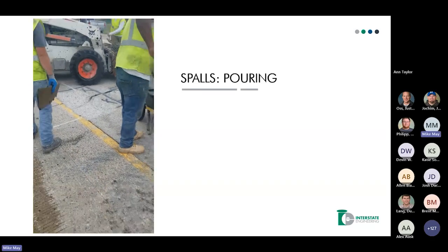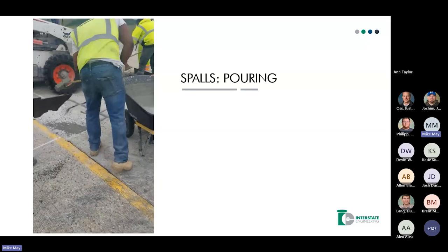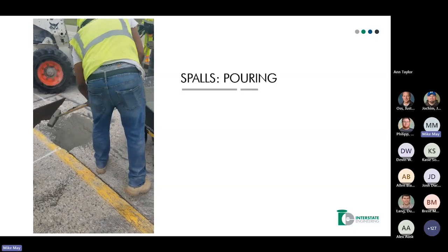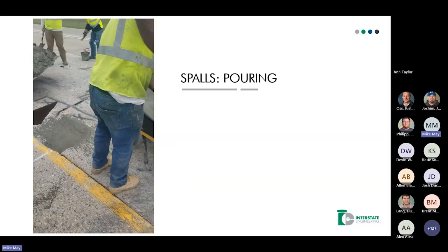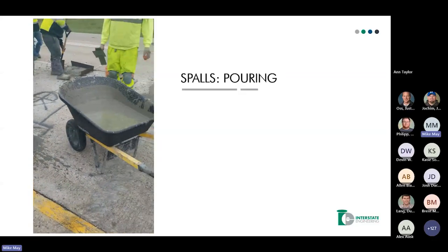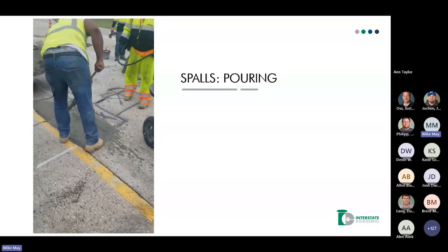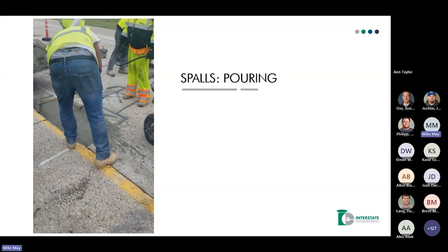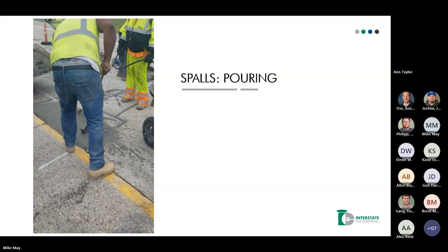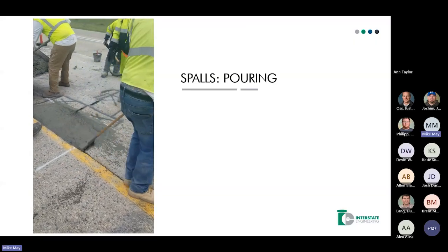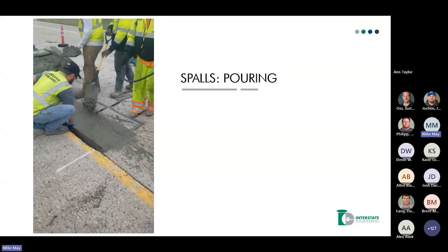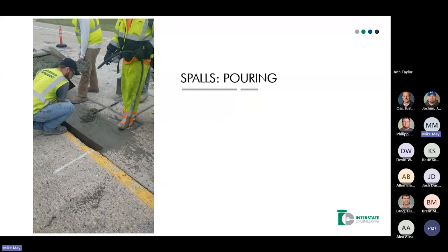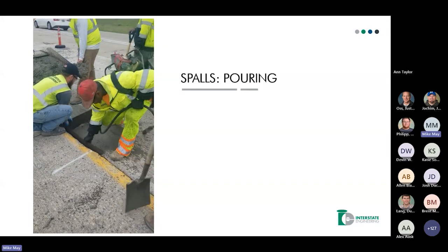And here's just another quick one here. This is showing the mixture for the grout. This is the key to make sure you get enough grout in there. Make sure you're getting enough cement paste down into that cavity, and then you can see them, they're right there to fill it up immediately. Gets kind of messy. And then obviously you've got to put your bond breakers in for your joints. I'll talk about that on full depth. That is a must.